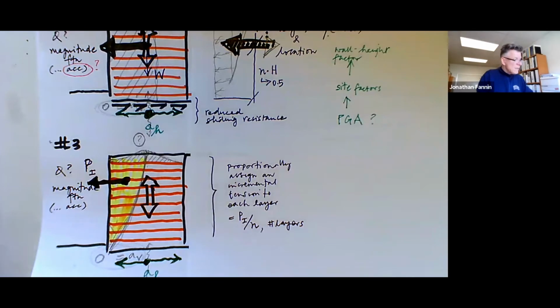There were structures that were loaded with accelerations assigned to sites that maybe about 1 kilometer away from where the structure itself was. So inferring that the peak ground accelerations at the location of the structure could be adequately described by measurements about 1 kilometer away. And there's an element of an if to that. But across the city itself, there's sufficient evidence to make the claim that many retaining walls were loaded in excess of the design code of the day in Christchurch when they were built.